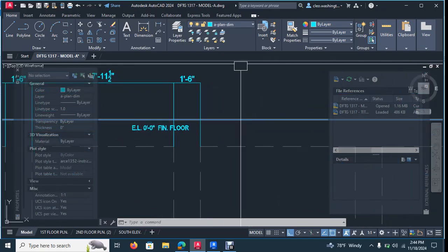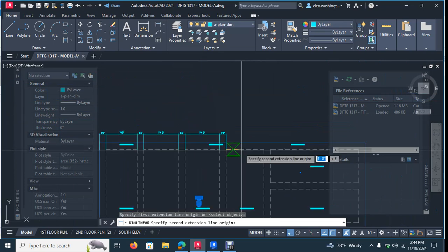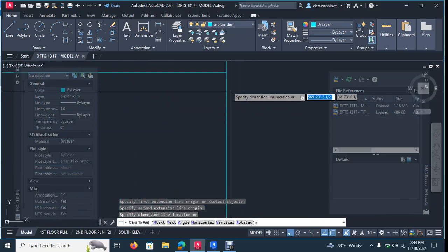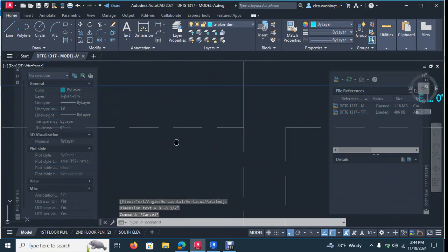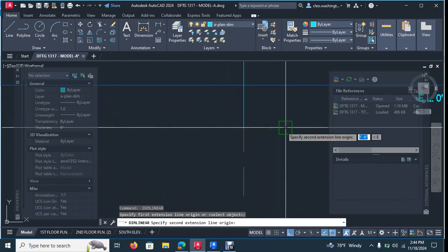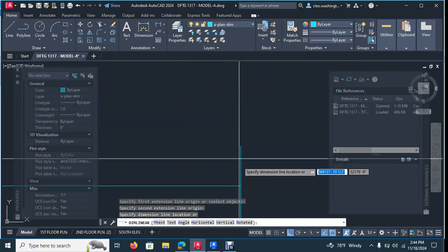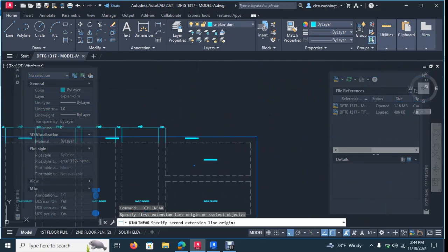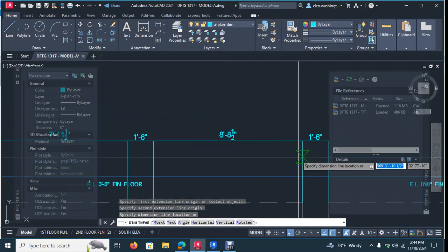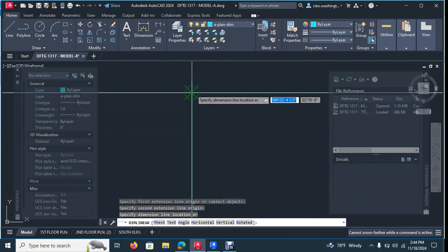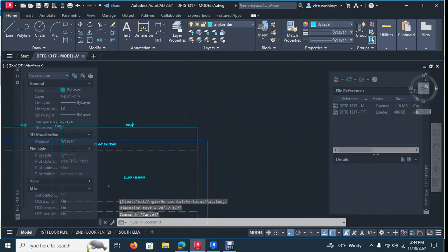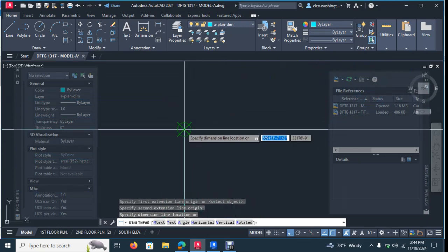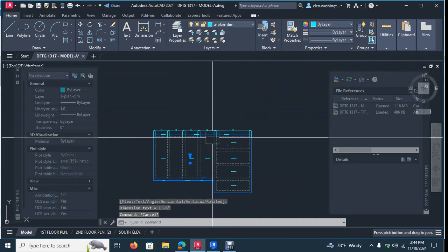And this is how I want you to dimension it. Okay, I'm gonna just show you guys how to do it, because this is foundation, so it's a little bit different from floor plan, but the principles and techniques are the same as regards dimensioning itself. I don't expect you guys to know what to dimension. That's why I'm actually putting these dimensions in here on the video, because you always will do a string of dimensions that dimensions the components, because you need to tell the contractor where to dig the grade beams. Then you need to do an overall dimension, right?